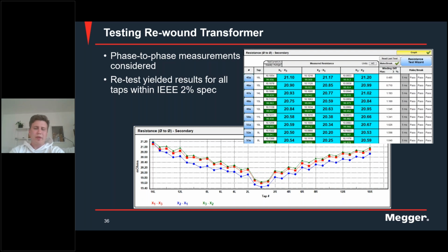So for example, if you perform the dynamic resistance test, they usually say that you shouldn't perform it with too low of a test current because you can get false readings, because you have a very thin layer of some coating that doesn't get burned through, and then you can get false interruptions. So that would be one example of a non-linear, so to say, resistor. But when you perform the winding resistance measurement, I don't think it's very common that you have these types of problems. So no, I don't think that will affect the measurement in any real way. But for the dynamic resistance test, it can be a bit more sensitive if you have a quite good connection only for low currents.